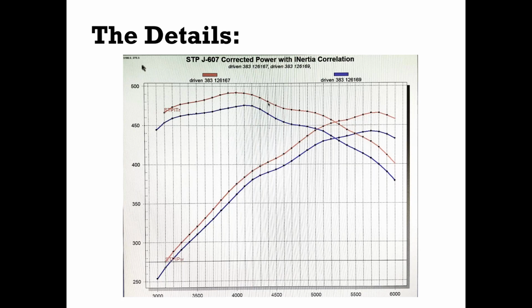And it just goes to show that you've got to keep up with little details like how much oil's in the engine. And it's really easy to say, well, I put in 6 quarts of oil. Well, if you put in 6 quarts of oil and you're doing, let's say, oil testing, you drain the oil out, did you get all 6 quarts of oil out? Probably not.